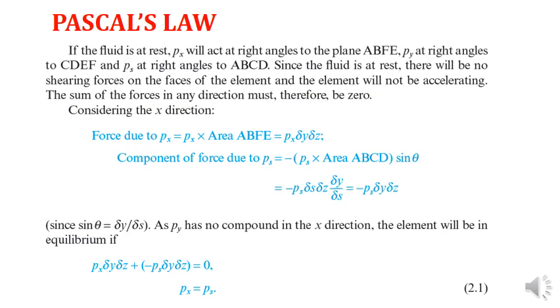We have discussed, if we define the center of this fluid at rest and draw a perpendicular, px will act at right angle to the plane AB, py at right angles to CD, and ps at right angles to ABCD. Since the fluid is at rest, there will be no shearing forces on the faces of the element.